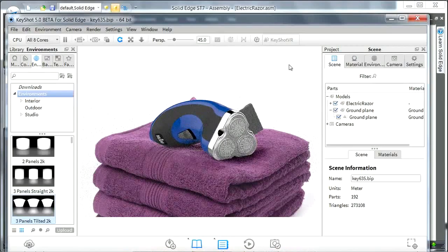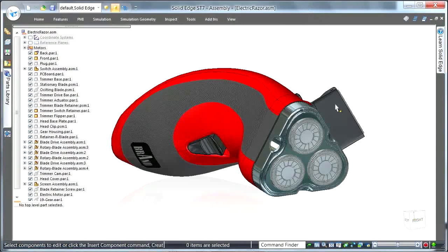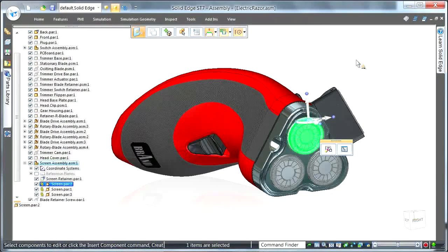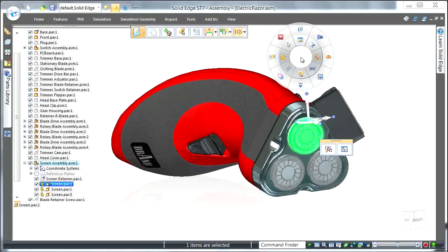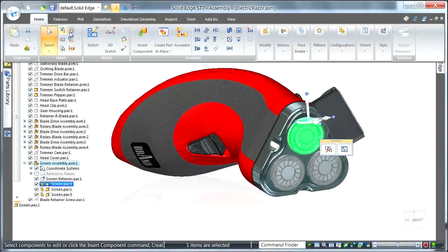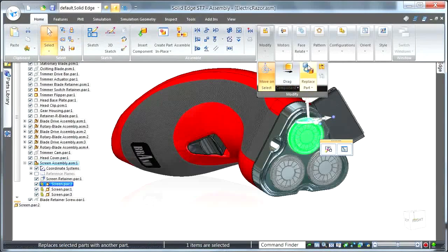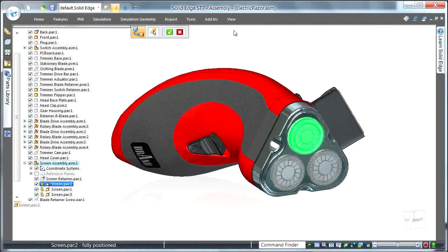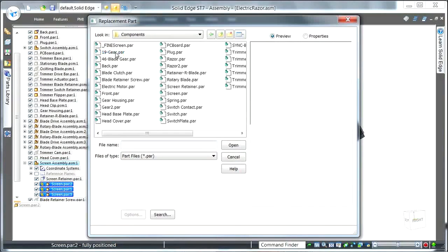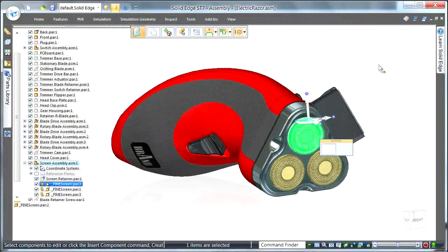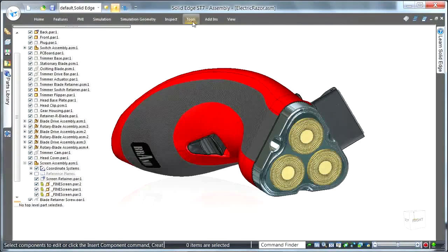If we want to go back to Solid Edge, maybe we need to make some design changes. So this is really important. How do we link with that Keyshot window? If we needed to change this geometry, that razor foil, so the geometry is going to change in shape with the cutouts, the appearance is going to change with this. And we want that to update in KeyShot. We don't want anything else to update because we've been playing around with it. So one button, update into KeyShot, just updates that for you. It's a real nice workflow for us here.